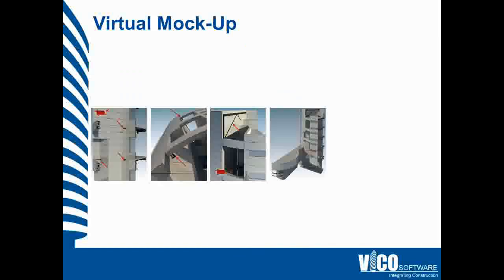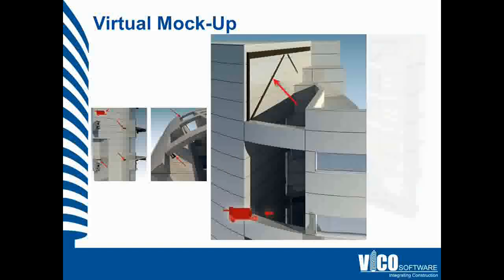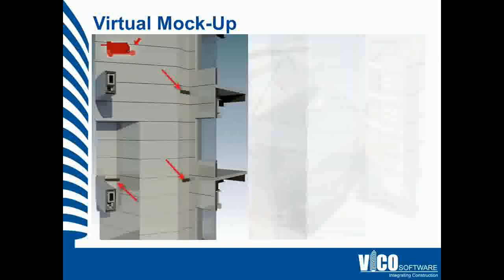During the project execution, we found that the steel structure wants to stick out from the building, and it wants to penetrate the metal panel system, which is obviously not good. So during our deep analysis and constructability reporting, we found these issues and reported them on site, and luckily we were in time, so the project team could put the metal panel fabrication on hold and redesign certain parts to order the matching metal panels.